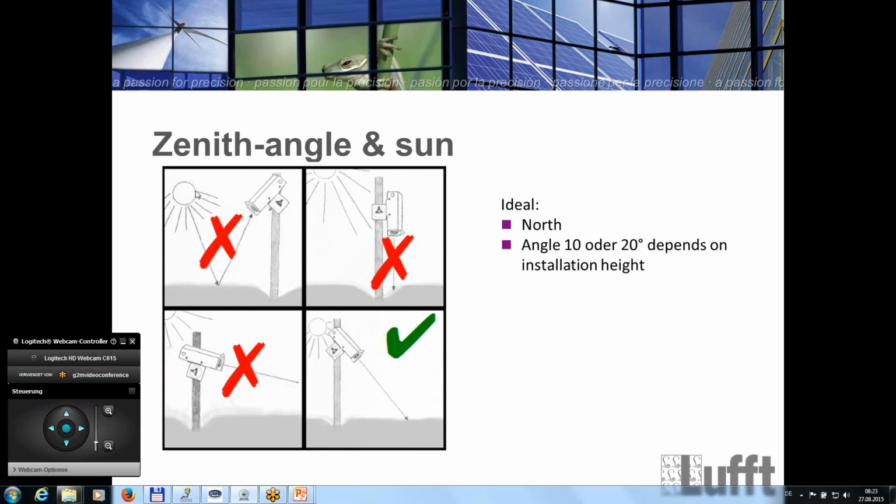You can directly see, for example, the heating cycle of the mast itself during a day. If you have installed the sensor at 7.5 meters height or something like this, the mast is definitely moving during the day. Especially if you use a horizontal bar on it, then it's more.